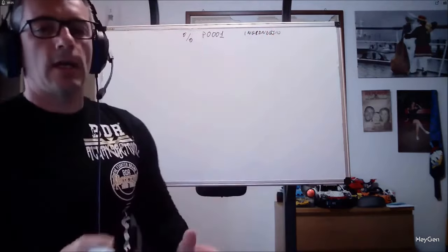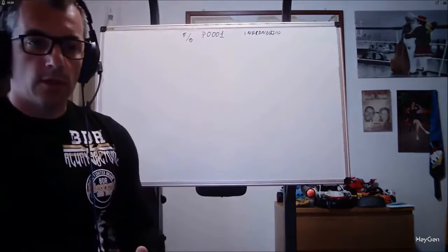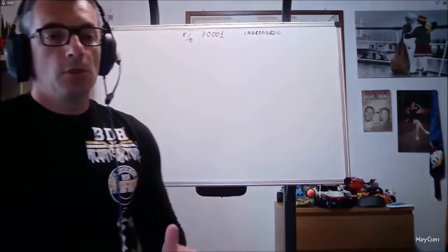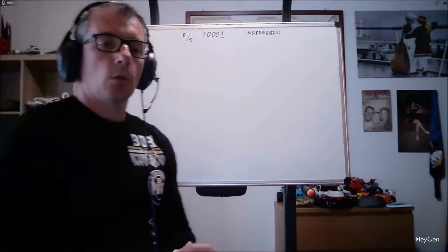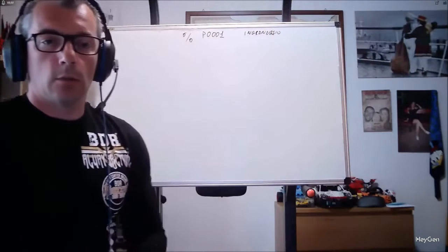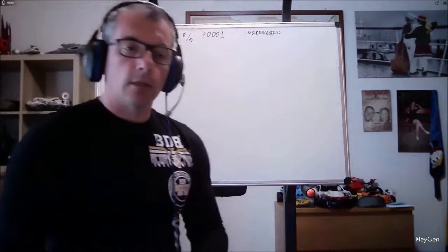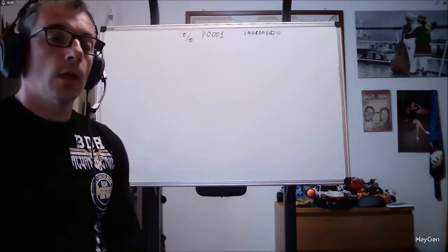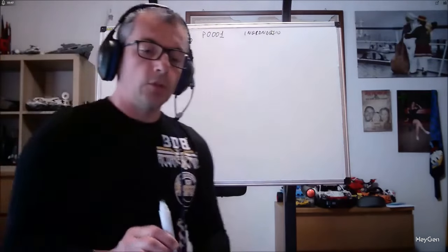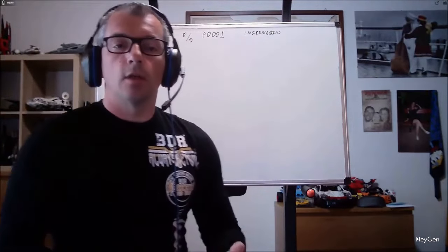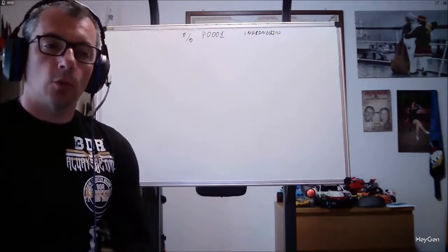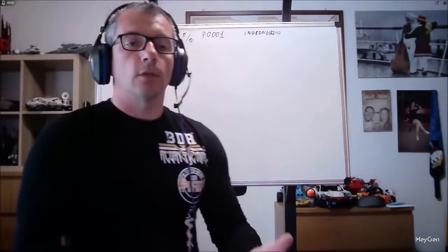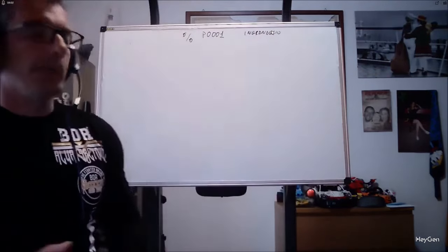I always recommend commenting the first line of your program in the most detailed way possible. So I always include the name of the client, that is, to whom I will sell the part, the code of the item, and if there are any specifications, that is, design modifications, I include those as well. Normally when a drawing undergoes a modification, for example, we have a ring with an external diameter of 100 and an internal diameter of 40 that is then modified to an internal diameter of 45, it becomes specification B. I copy the program, make a copy, and keep the old one, just in case they ask for a replacement.